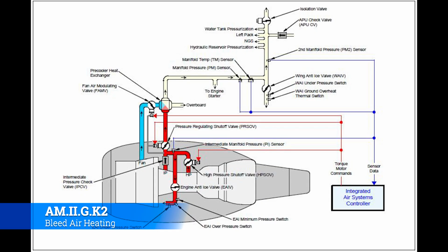Okay, bleed air is often used to heat the cabin whenever there's not another option for heating available. The way this happens is that you take bleed air off of the engine and mix it with cool outside air, and through a series of valves and then ducts it eventually gets delivered to the passenger itself. Pretty easy solution. You take the bleed air, which is super hot, and the cool outside air, and you open a valve with more outside air than bleed air, and that lowers the temperature through that mixing valve to a comfortable level inside of the cabin.